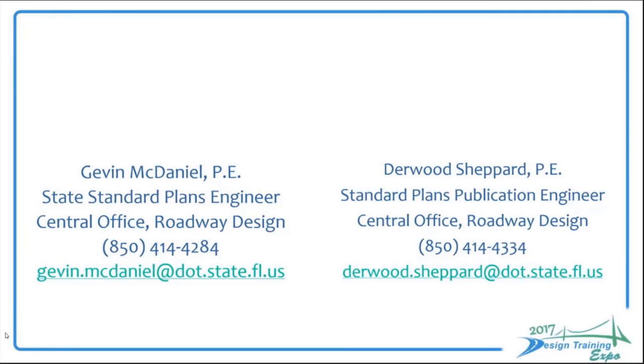So moving forward, there will be a new requirement that for all box culverts, regardless of whether there are any other structures-related or bridge items, there will always be a structures component to the plan set or the plans package, and that's where the box culvert data tables and report of core boring sheets will be. There's no real change in the format of that information at all. It'll just be those couple of items, and that's it for box culverts.